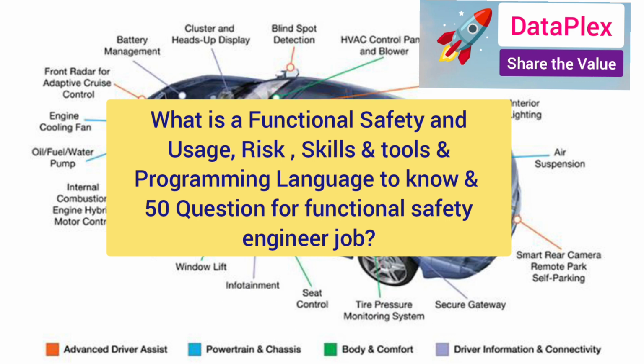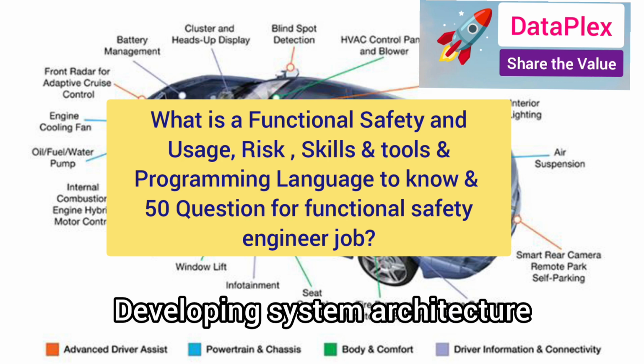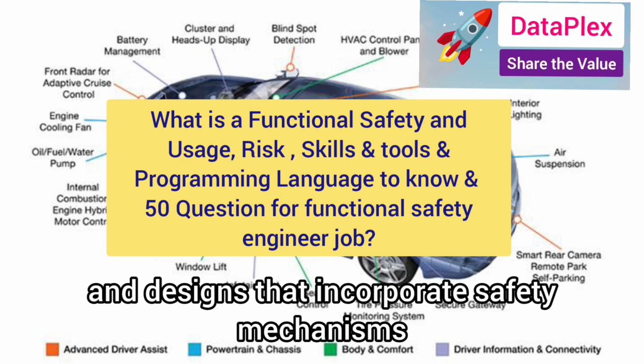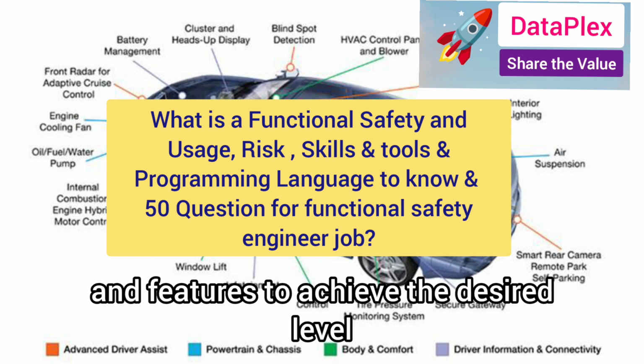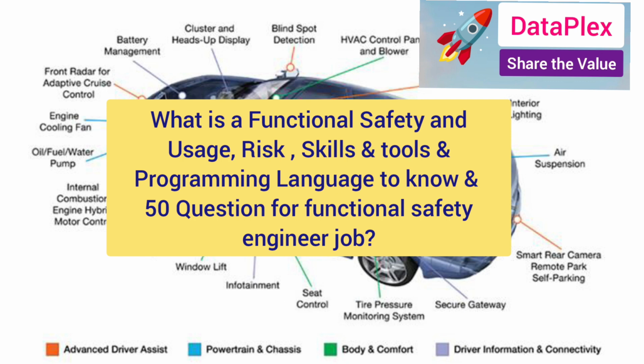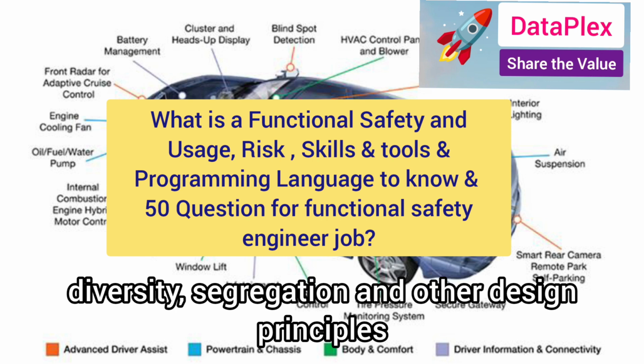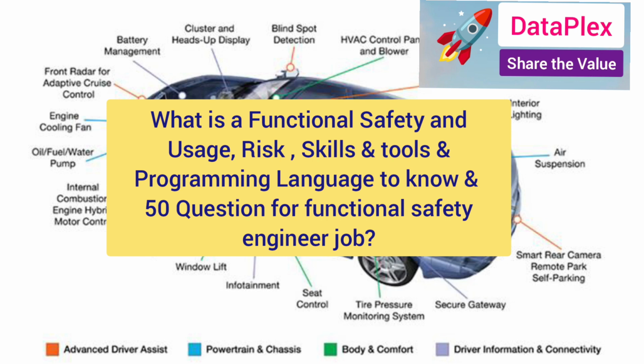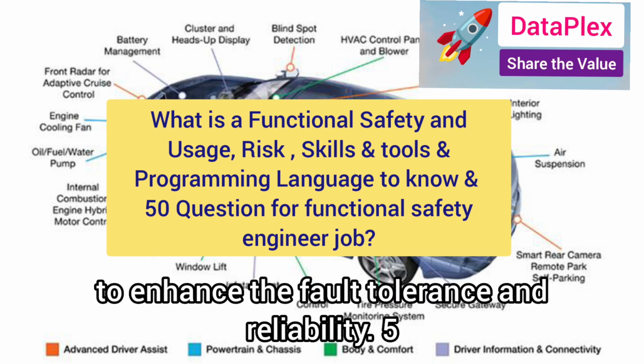Number four, safety architecture and design. Developing system architecture and designs that incorporate safety mechanisms and features to achieve the desired level of safety integrity. This includes redundancy, diversity, segregation, and other design principles to enhance fault tolerance and reliability.